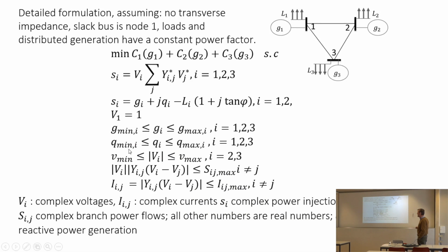Why do we care about voltage magnitude being between minimum and maximum bounds? Well, one of them is the quality of service. If you pay Romande Energie to get a power service, you assume you will get 230 volts between phase and neutral, right? If you get only 5 volts instead of 230, probably some things will not work. So some of your machines will not work.